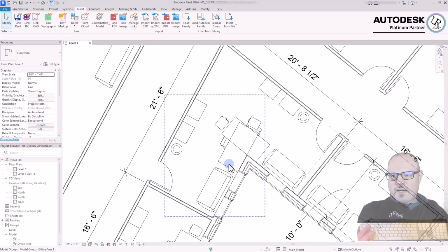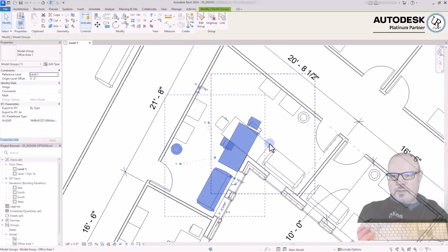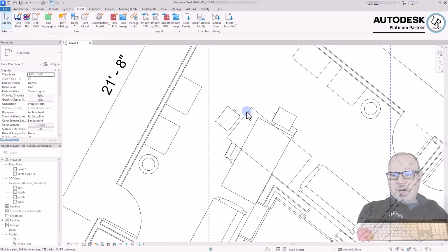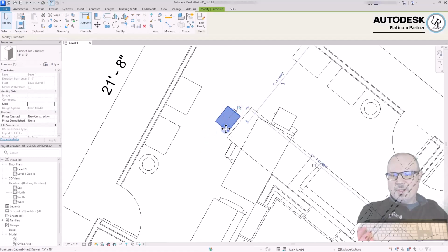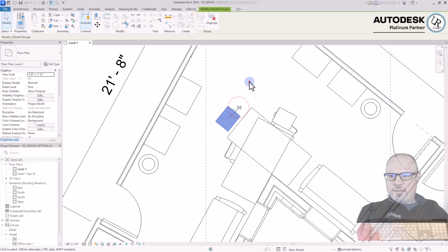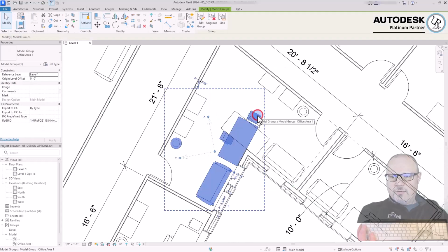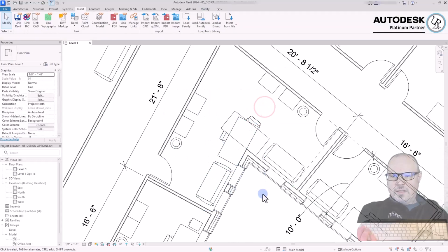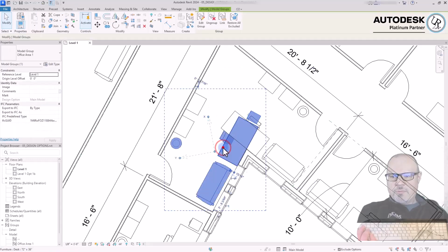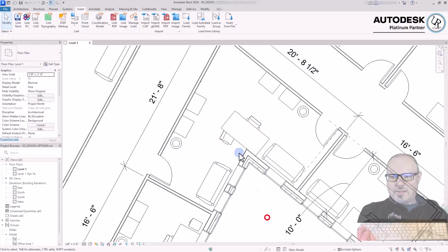Coming back into this environment where these elements are overlapping, as you hover over an object of the group, you can hit the Tab key and select that object separately, and then you see this little icon that says Group Member. Click icon to exclude in this group instance. Select that, deselect the whole group, and the object has been removed or disappears. Continue that over and over again. You are not deleting the object from the group, you're just removing that object from this instance of the group.